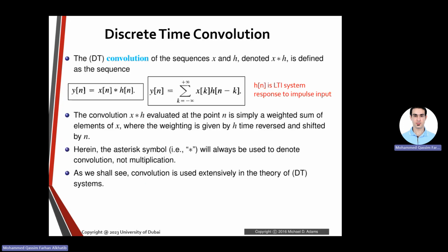All right, so what is convolution in the discrete time domain? As I mentioned, y of n is x convolved with h. This process is the summation, that's why they call it the convolution sum, from negative infinity to infinity, x of k, h of n minus k. Notice one important thing: the domain for x and h has changed into k. Even if your functions are given as h of n and x of n, the first thing we'll do is transform these domains into another domain, k, which is the same variable but a different representation, to avoid confusion with the original index n.